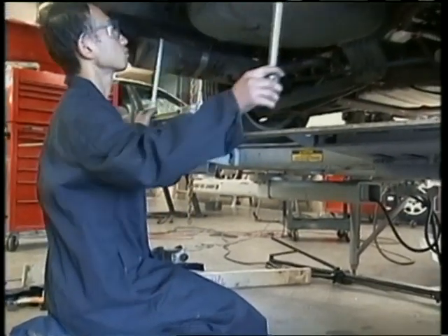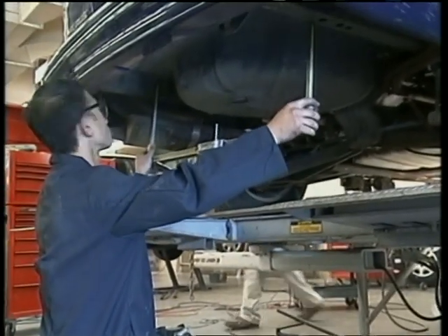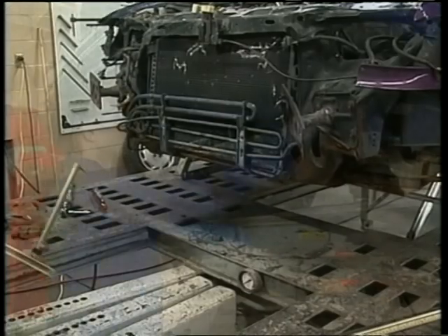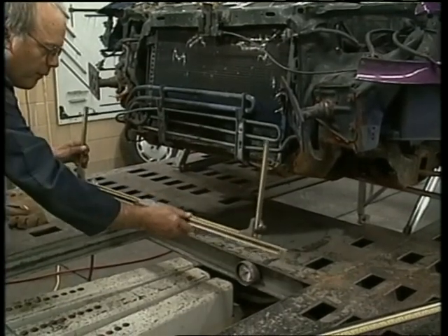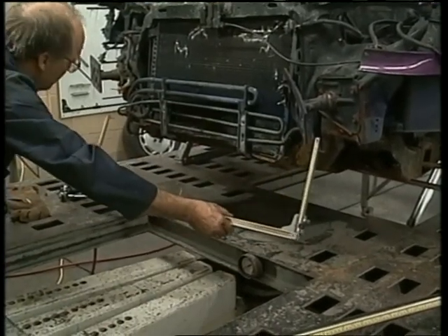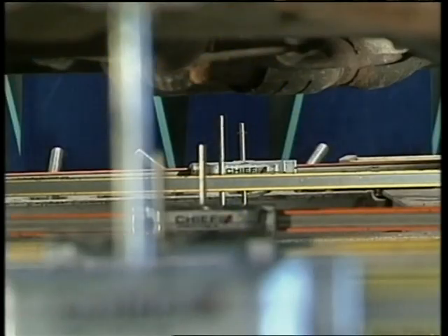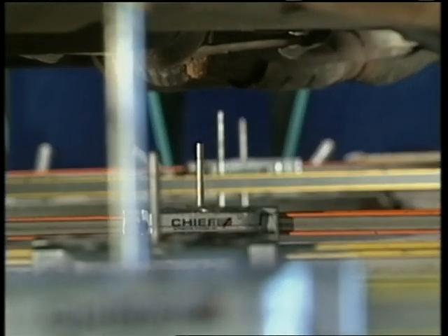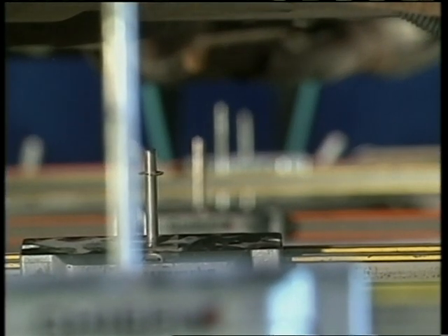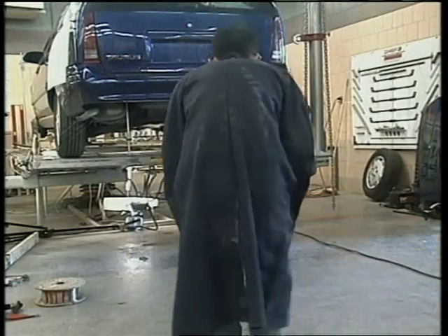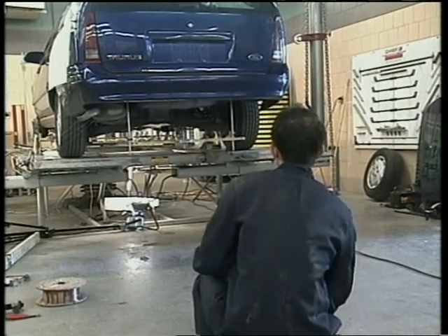Attach 4 or 5 gauges at control points along the entire length of the car. Hang at least one of the gauges at the point of obvious damage. After all the gauges have been hung correctly, stand directly in the middle of the vehicle. Scan the centering pins with both eyes to make sure they're in line. Pins that are not in line indicate frame damage. The further you stand from the gauges, the more accurate your assessment will be.